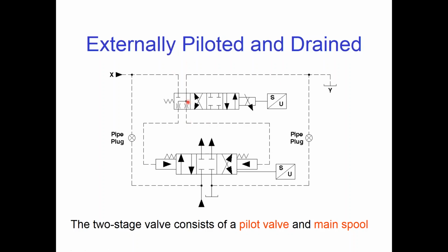It bleeds relatively slowly. We don't want it to slam into its closed position. So you see the little flow control symbols drawn in here. That means that it's not going to just slam closed and break something, but it will slow it down and then rapidly bring it to a stop.